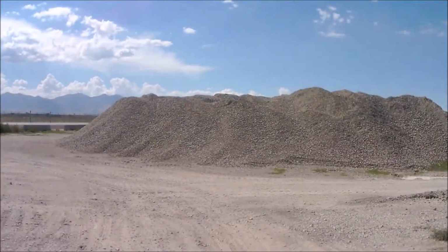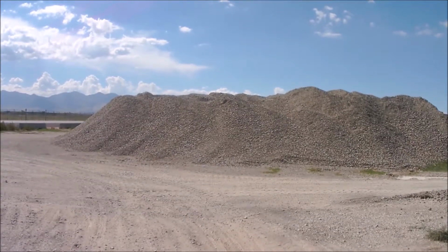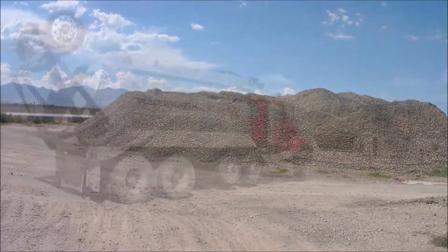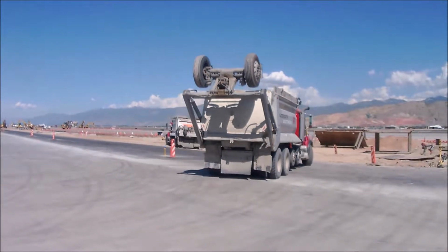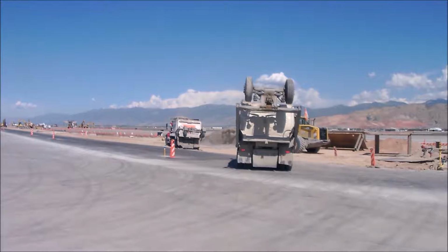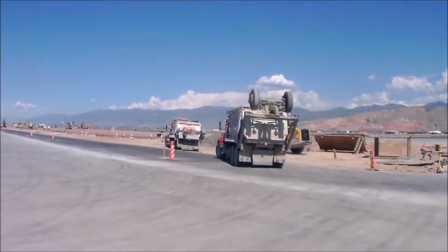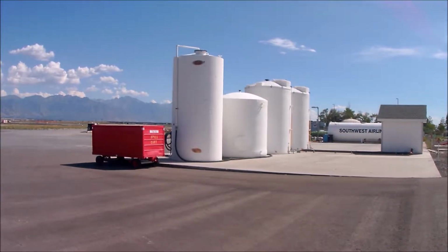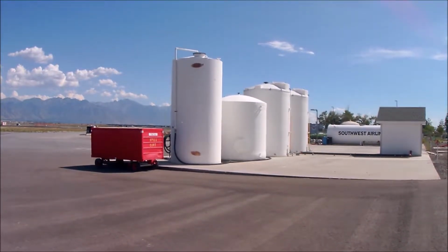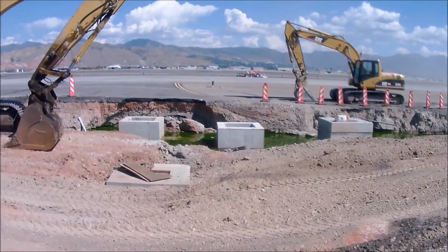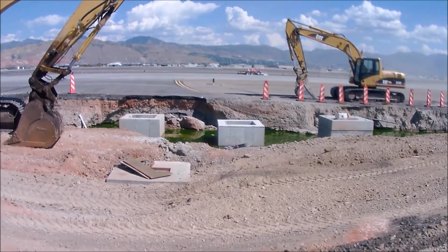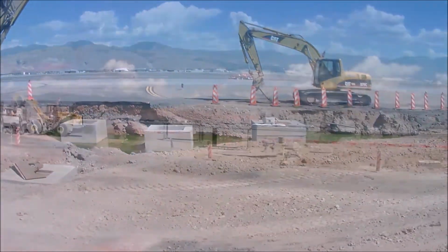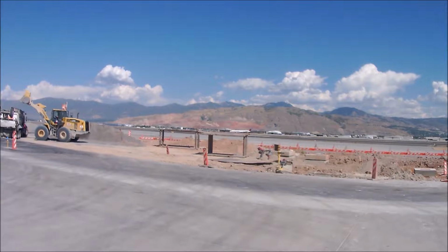Examples of potential energy on our site include electrical, mobile equipment, stored liquids, stacked aggregate, charged utility lines. Controls will vary depending on the type of energy being controlled. Examples include blue stakes and hand digging for utility lines, wheel chocks for vehicles and equipment being maintained, LOTO for maintenance, MSDS for handling chemicals, restricting access to aggregate storage areas.